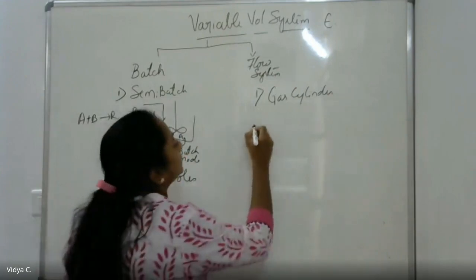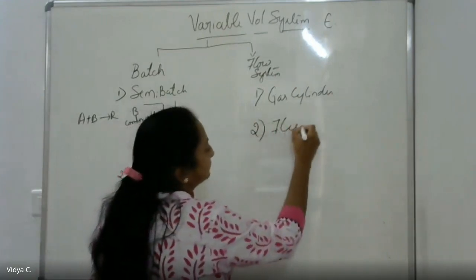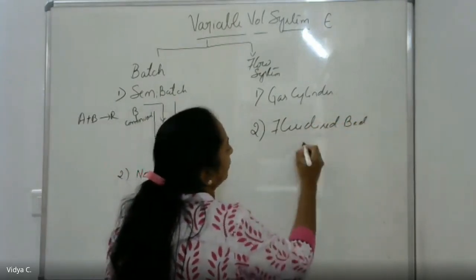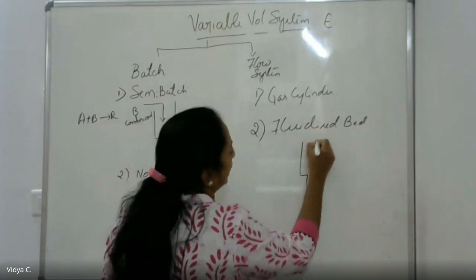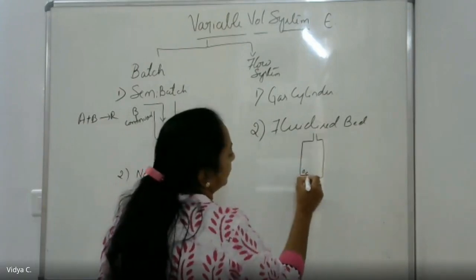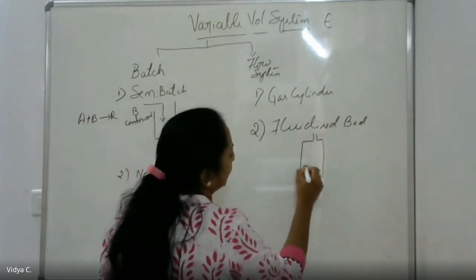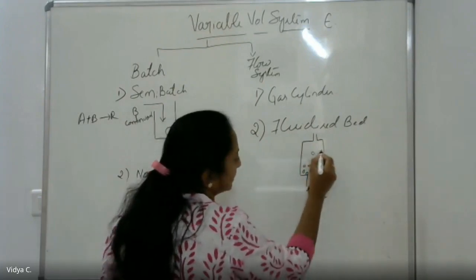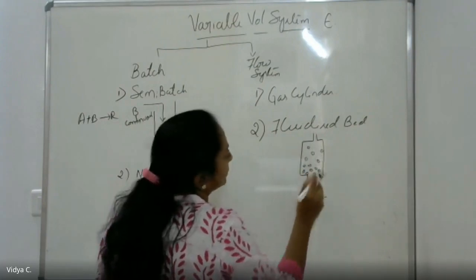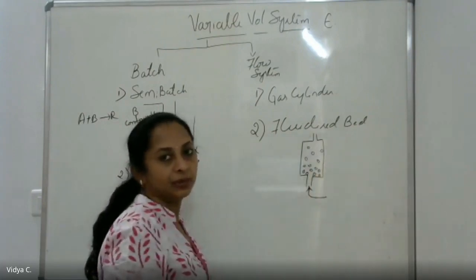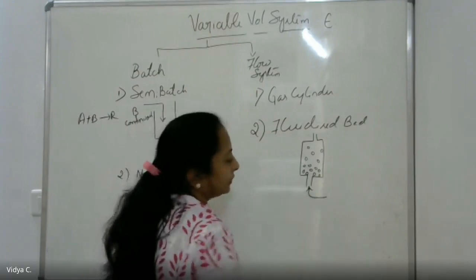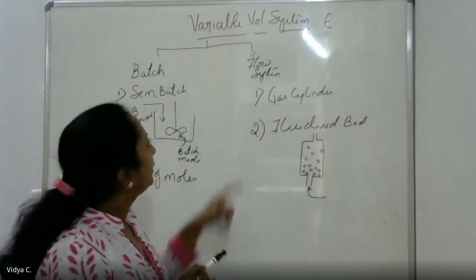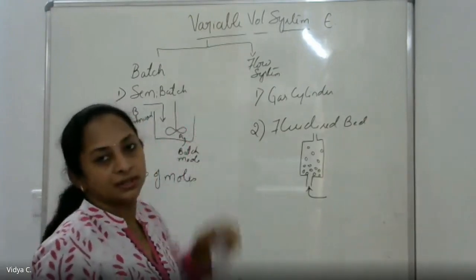Okay. Second one, a fluidized bed. You know what's a fluidized bed? Fluidized bed is one in which the solids are actually packed here. If it is just packed, we call it packed column. When the reactant enters in, these go to fluidized state. So the volume here varies with the inlet given to the reactant stream. So this is one example for a variable volume flow system.